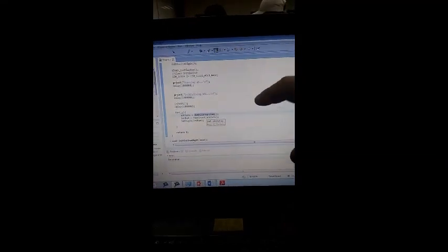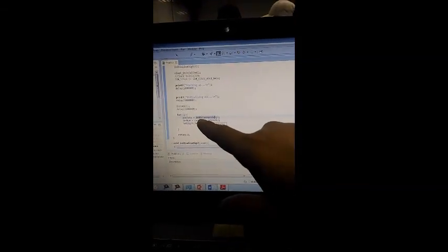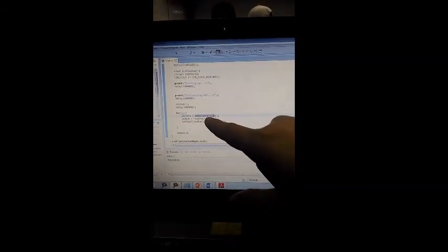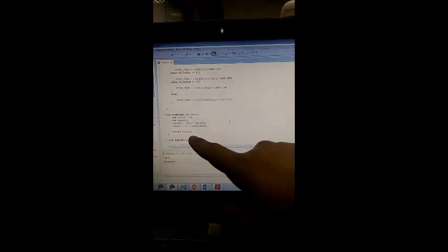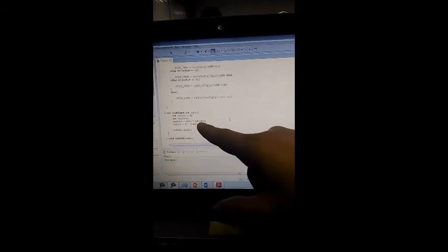I would like to talk about Lab 3, Part 3. Lab 3 is about the combination of Part 1 and Part 2. The only difference for this is the ADC conversion is provided to the rate input. And then we set the new data equal to data multiplied by 10 divided by 1023.